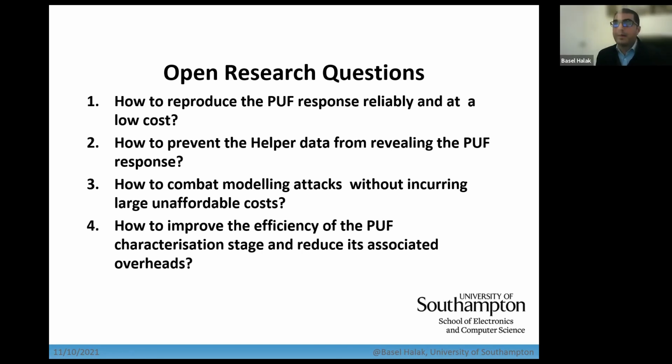I think intuitively, the metric for the PUF is not whether there is a dependency between input and output. The metrics we use to assess the PUF are basically whether it's unique, whether it's reliable, and the entropy of the generated response. The response is supposed to be random but reproducible, because if you apply the same challenge, you should be able to reproduce the same response. Yeah, I understand. But when it's used in security applications, we sometimes need to assume they have some security properties. Yes. And those security properties probably need to be defined more explicitly and match what exactly the PUF implementation can actually provide.